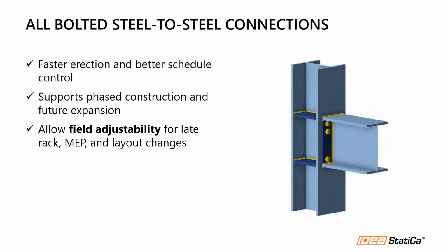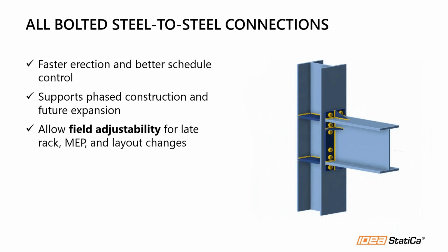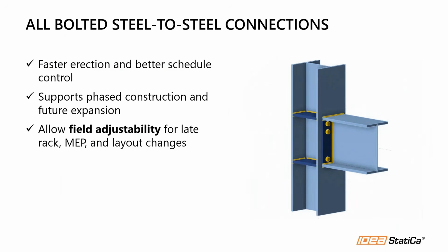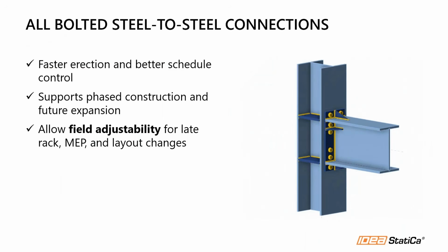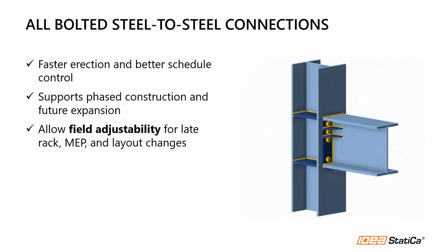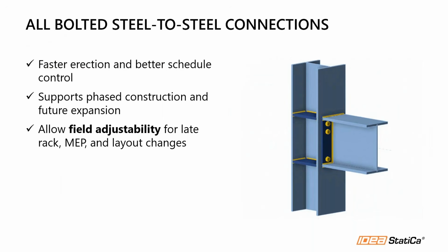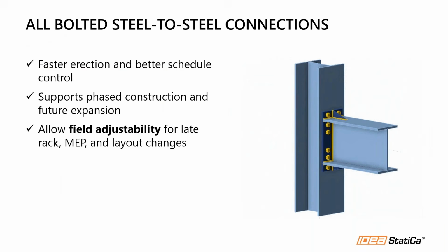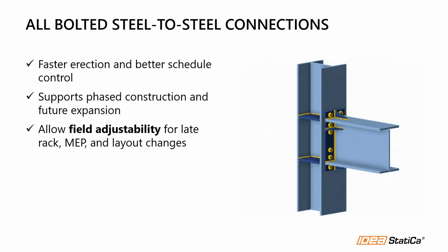All right, so the bolted connections here, they're able to reduce on-site installation time by reducing additional steps, such as field welding or extensive detailing that has to be done for those connections, which in turn helps to keep fast-track projects on schedule. Data centers are also built in phases, so these bolted connections allow the expansion of new areas to be added without redesigning from scratch. And since late changes to rack layouts, MEP routings, or equipment loads can sometimes be common, bolted connections provide that flexibility to accommodate those changes without delaying your construction.